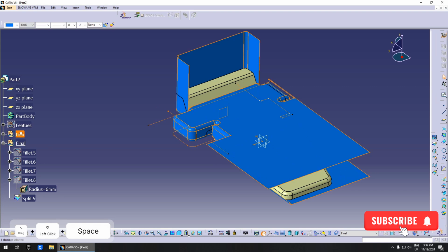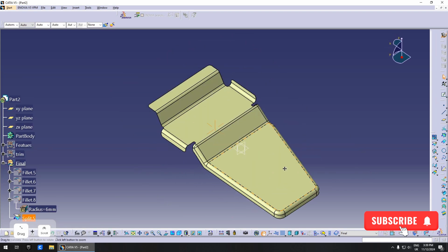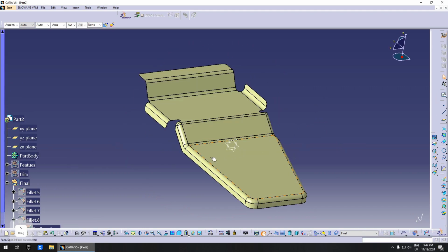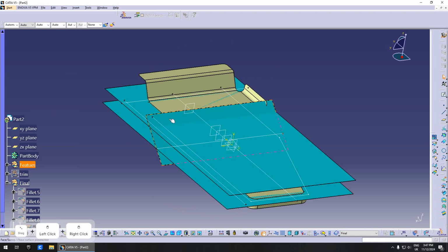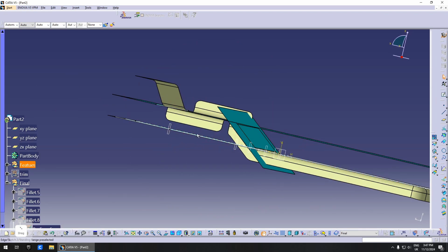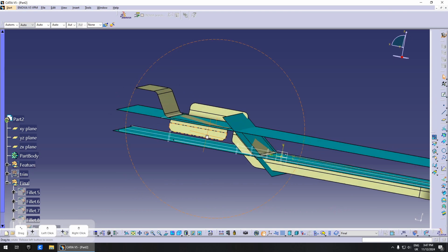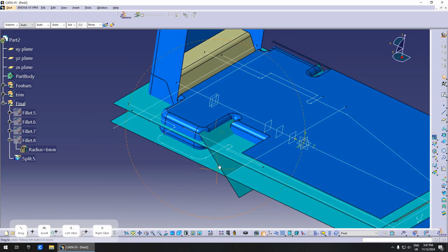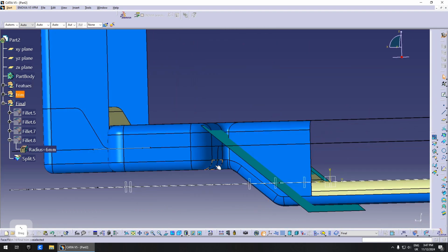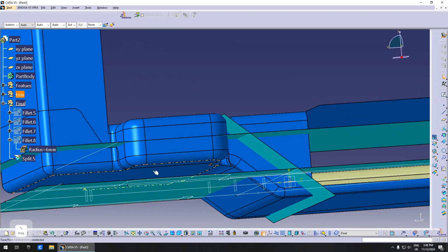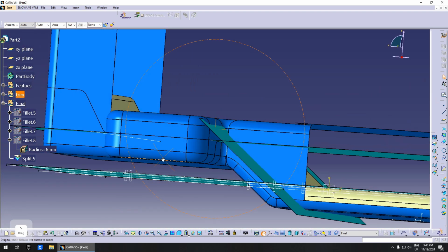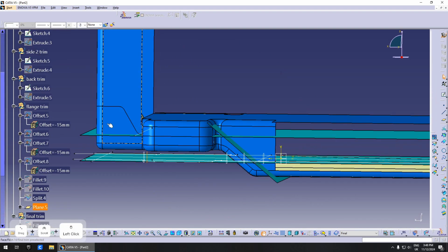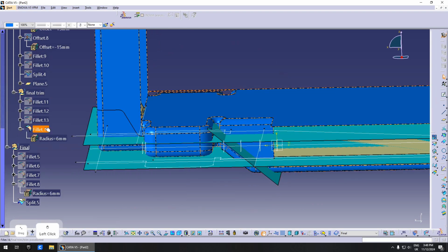We then go ahead and hide everything else, and this is perfect. One thing we noticed is that we have accidentally cut this leg off here, and we're going to find out why in a minute. It is because we used this bottom surface for cutting the flange that we didn't need to do. We extended it too much. So in order to fix that, we go to where we design our surface.